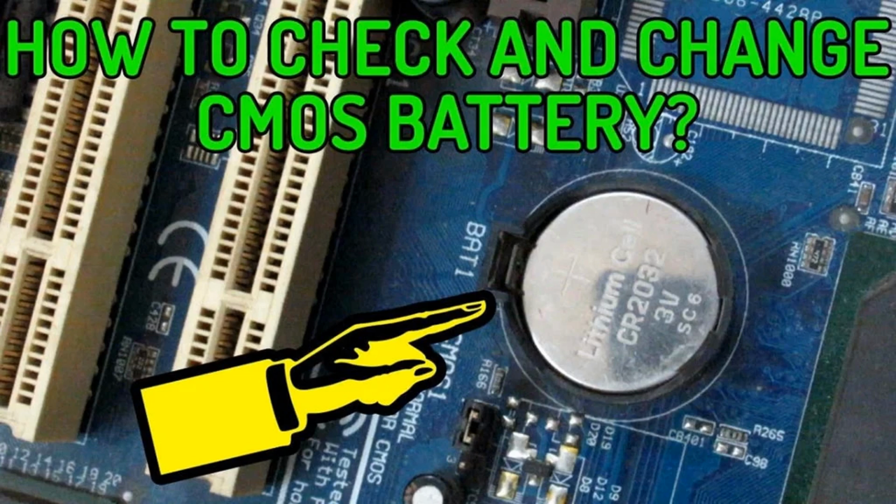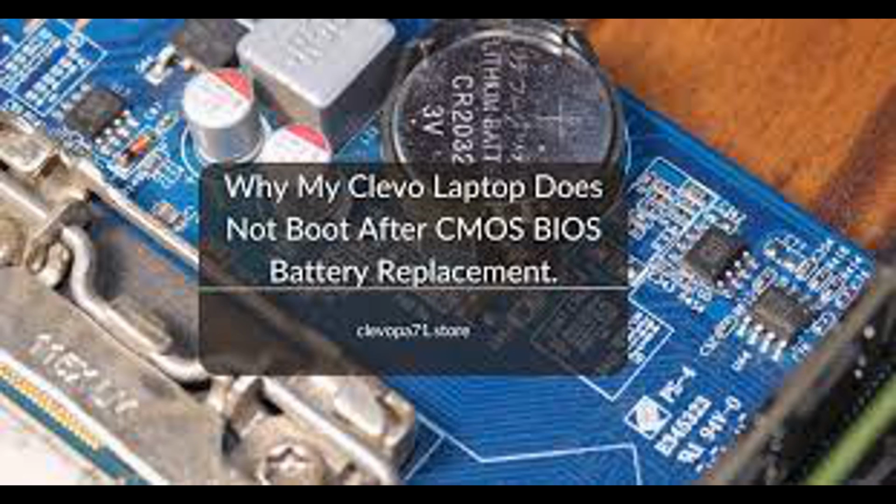Channel. The channel is the region between the source and drain terminals through which current flows under the control of the gate voltage. In a MOSFET, the channel can be either an electron channel, N-channel MOSFET, or a hole channel, P-channel MOSFET, depending on the doping of the substrate and the type of MOSFET. Gate. The gate is a terminal that controls the conductivity of the channel. It is separated from the channel by a thin insulating layer, typically made of silicon dioxide, SiO2. Applying a voltage to the gate creates an electric field that modulates the conductivity of the channel, allowing the MOSFET to act as a switch.